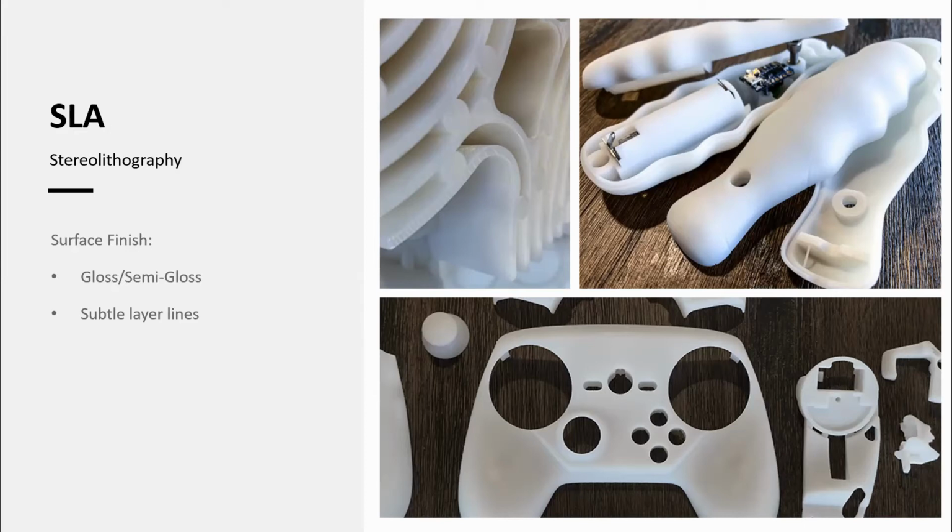Because of this nice smooth surface finish on SLA parts, one of the best applications that we use SLA for is prototyping and fit checking parts that are intended to move on to additive manufacturing. It's also a very good choice for testing assemblies before moving on to production.